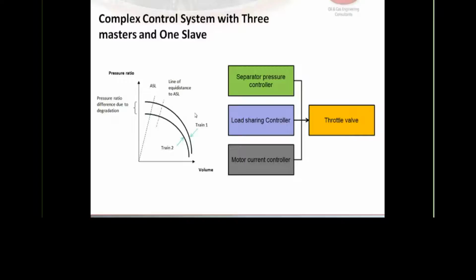So the only way that works is that basically the anti-surge valve will have to come in, with the train going into surge sometimes. Then the anti-surge valve will open, and the load sharing will obviously become disconnected. It will try to compensate, and it's just a cycle. It just starts again. But we'll see all these details in the next few slides.